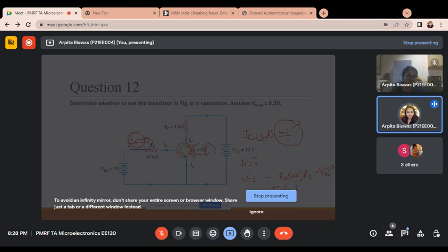When the transistor is in saturation, you have to assume that the transistor is in saturation, then calculate from there. So what is the value of this? This will be 9.8. Somewhere you have to calculate how this 9.8 milliampere is coming. And the IB value is 0.19.